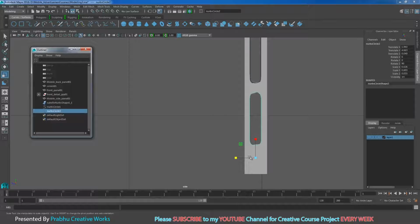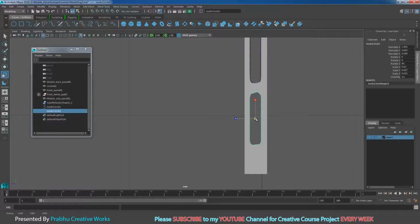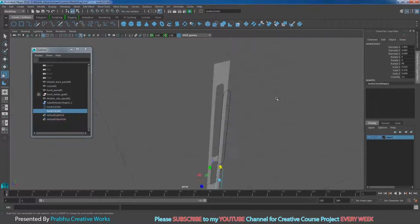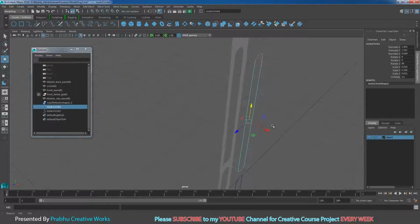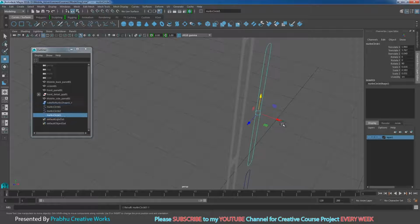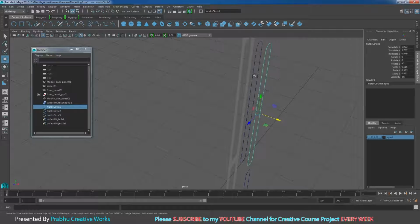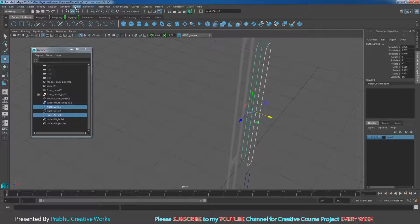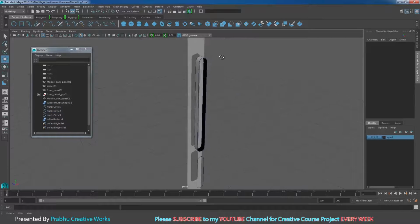Select this curve and go to modify and choose center pivot. Now I want to scale a little bit in and scale a little bit in Z. I will scale a little bit in X. Now go to perspective. Now I select this object, press W and press Ctrl D on the keyboard. You want to move it in X. So I will select this object and shift select this object and go to surfaces and choose loft. Now you have that one.